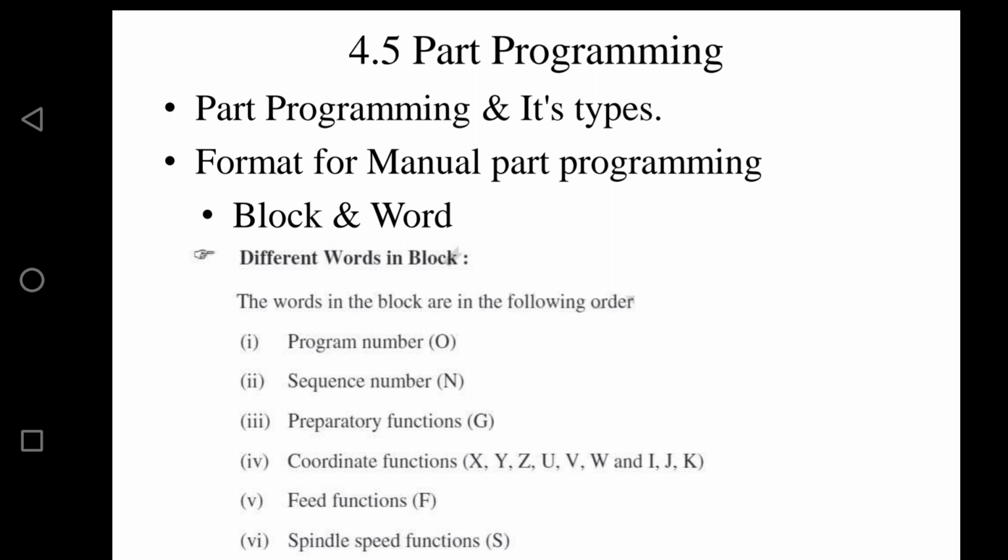If you have a program based on the machine tool, then it comes under O9000 to O9999. So it is a 4-digit number, which indicates it has 9999 different programs. So that is about the program number. Before going for any programs or operations, you have to write the program number first.